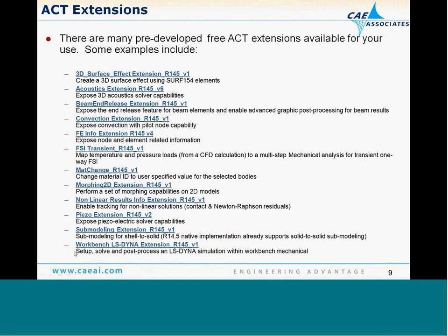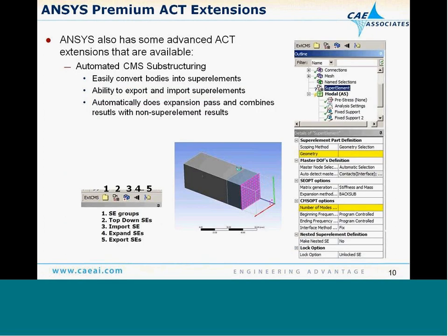It lets you set up, solve, and post-process the LS-DYNA simulation, which is the LS-DYNA export, which just writes out the .k file. You can actually do some more things and read the results in there. But other ones: FE info, change materials, do some 2D morphing of nodes, and submodeling. So there's a bunch of ones already up there, and hopefully they'll just continue to grow in the future as more people submit extensions to that.